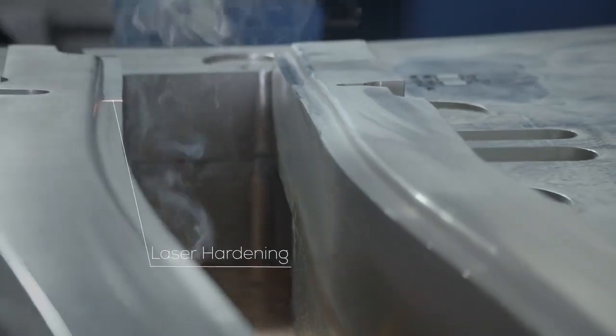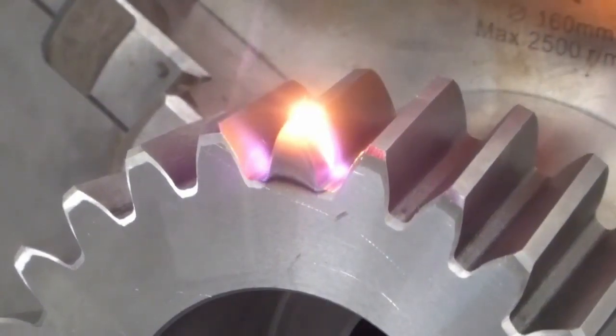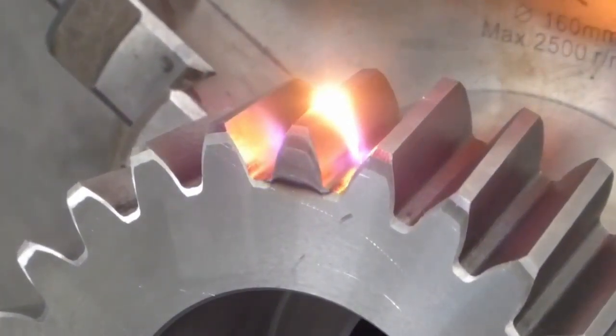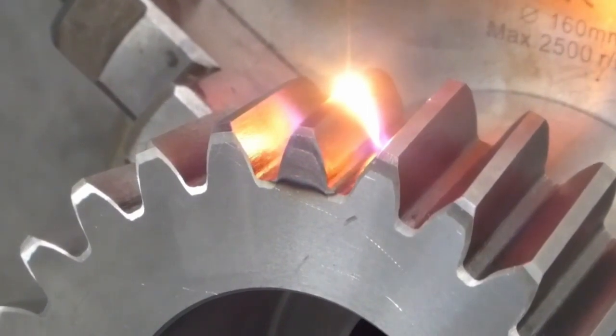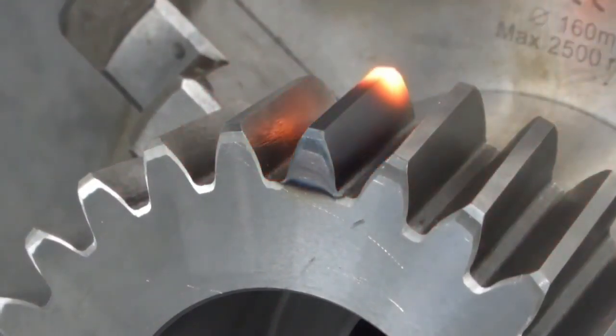The area under the laser beam instantaneously reaches the desired temperature. The laser beam is programmed to move across the surface of the workpiece. The effects of the laser hardening process can extend between 0.1 to 2 millimeters into the workpiece, depending on the material and the laser process parameters.